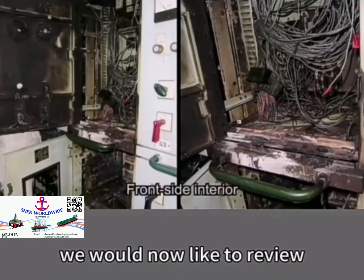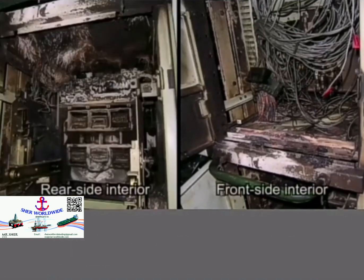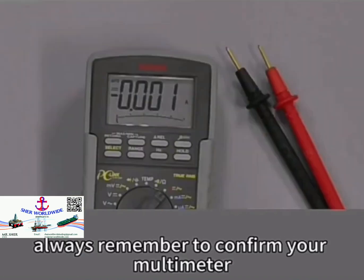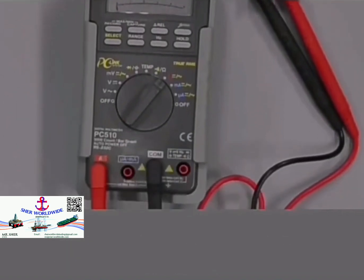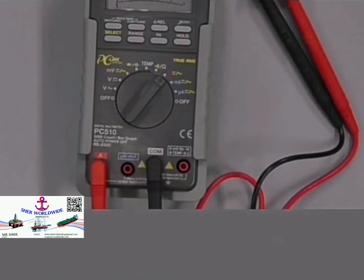We would now like to review several accident case studies to help you better appreciate switchboard best practice. Shown here is a fire that broke out in the switchboard. Improper use of a multimeter is the likely cause. Always remember to confirm your multimeter's settings before you begin to measure. Improper use of a multimeter will not only break the multimeter, but also damage the target equipment.